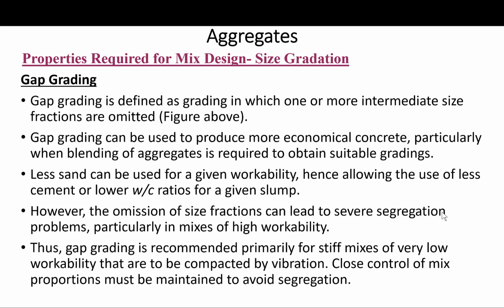So in practice, this approach I just mentioned cannot be used, because the resulting concrete does not have adequate workability. So this does not mean that consideration of combined gradation is without use. For example, combined aggregate gradations can be used to optimize workability, economy, and strength, as we have seen before. So let's look at some other grading methods.